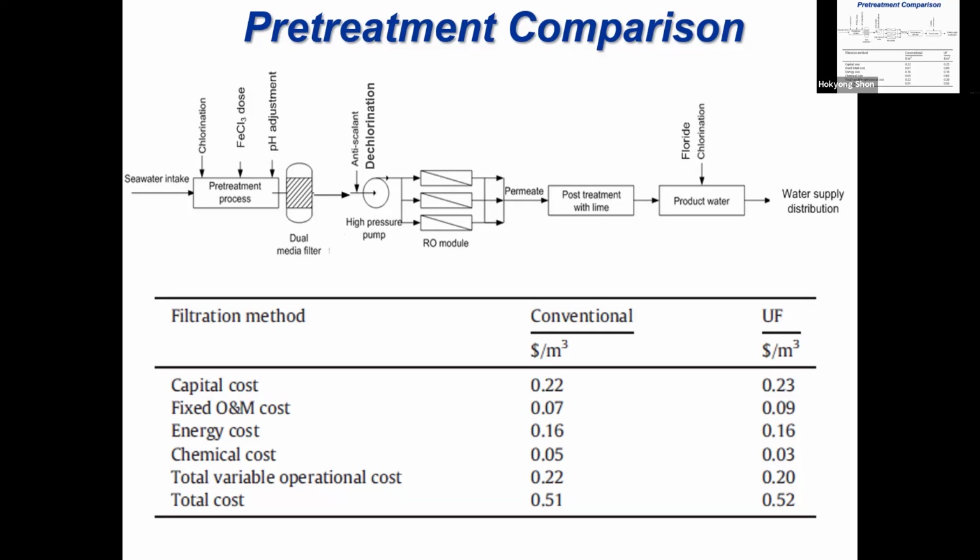You have your fiber, and you have pores here. You just suck the water, then the water will flow inside the hollow fiber, and you collect the filtrated water. This is the pretreatment because you remove all the large particles, and only the dissolved ions pass through this pretreatment membrane. Compared to sand filtration, sand is the largest size.